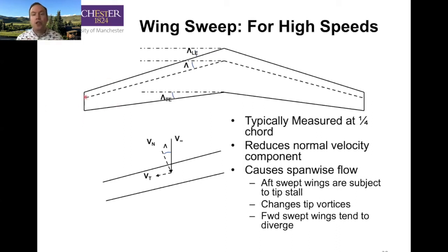That causes two problems that we don't see in a straight wing. One is that if this tip stalls before that tip, we get a rolling moment. So when we stall an aircraft like a 737 or an A330, we can get quite large excursions in bank angle. If you look at the flight data recorders from Air France Flight 447 over the South Atlantic before it crashed on its way from Rio to Paris, you'll see that at some points they were at 60, 70, 80 degrees bank angle.